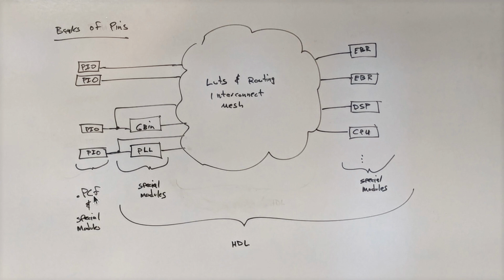All right? Now, I've drawn them in a square box here, along with these other square boxes we'll talk about in a second, because you can also use what we call a special module inside your HDL language you've chosen. In my case, it's Verilog. So if you don't know what a module is yet, we'll see that soon enough. The short of it is, anytime you express a piece of a circuit, you're creating a module. Modules have inputs and output signals, and then it has combinational and sequential logic within it to express the functions you want to achieve.